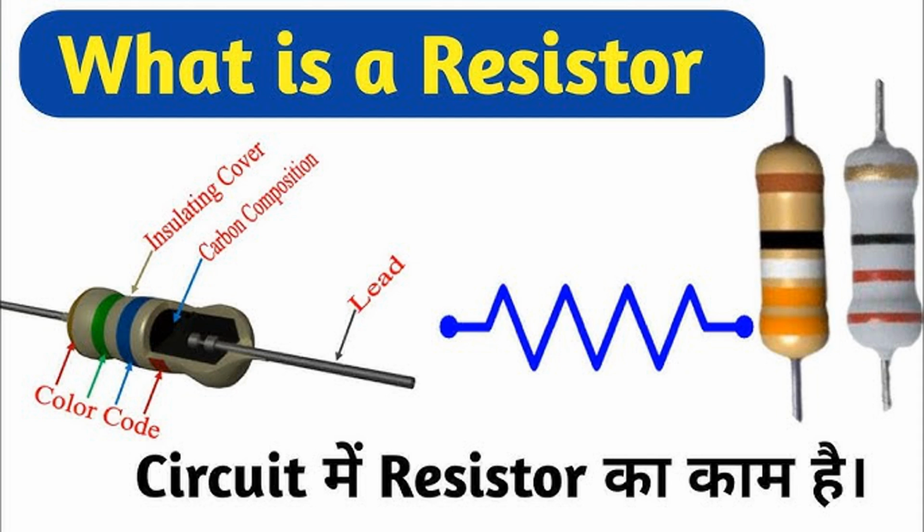Understanding pull-down resistors. Purpose: A pull-down resistor ensures that a digital input pin reads a low, logic 0 state when no active signal is present. Without a pull-down resistor, the input might float, potentially picking up noise and causing unintended high readings.